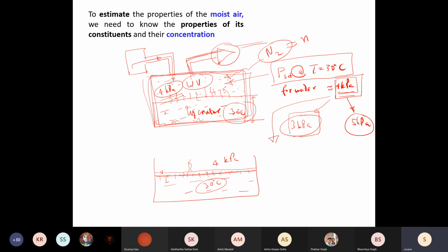Whereas in boiling, you start to see vapor bubbles even at the bottom surfaces. All the while, when evaporation is happening, you will see that there is no vapor generation in the bulk fluid. But when boiling happens, you will see that the vapor bubbles start to nucleate.